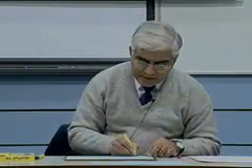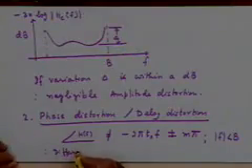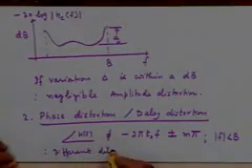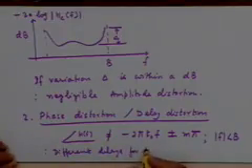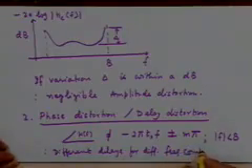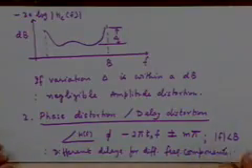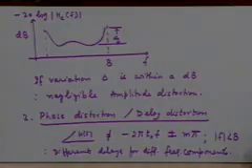So if this linear characteristic does not hold, it implies different delays for different frequency components, and that is why we also call it delay distortion, right? If every frequency component present in the message signal undergoes the same amount of delay, there is no delay distortion, no phase distortion. If different frequency components undergo different amounts of delay, there is a delay distortion.